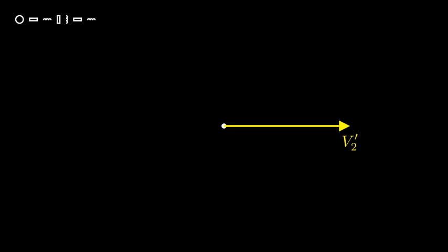The most logical place to start is at the end, the voltage being delivered to the load. We'll call this V'2, the secondary voltage referred to the primary side. Since we can orient our drawing any way we want, let's place this vector horizontally as our reference.